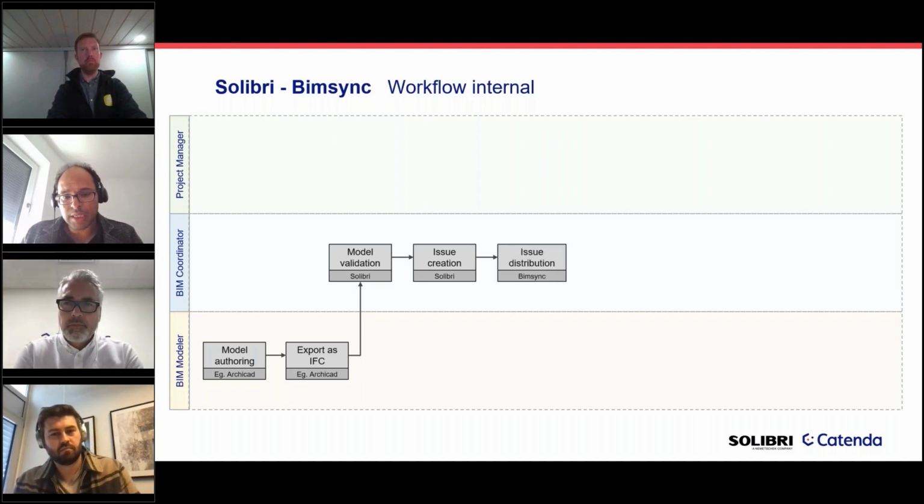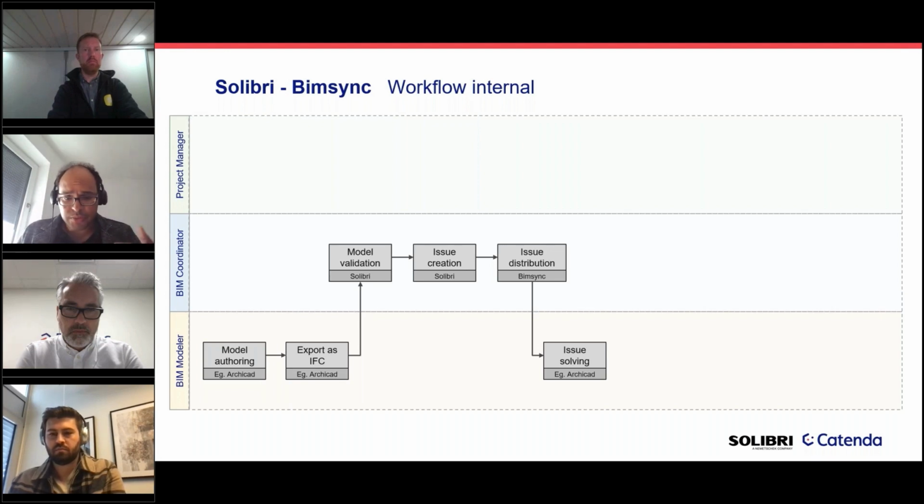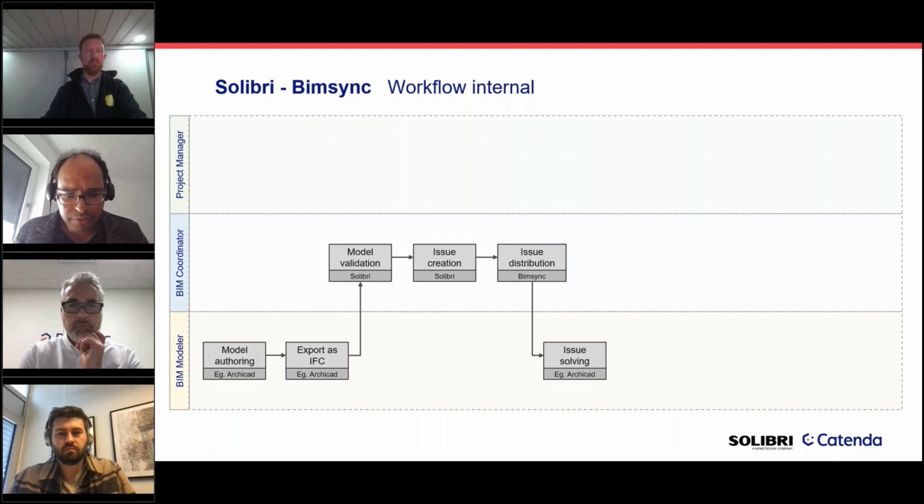The issue distribution, this is when Bimsync comes in, because we want to make sure that the issues are not duplicated, that if I have one issue, it remains one issue no matter how many people or project parties are involved in it. And then once the issues are distributed with Bimsync, I could open the issues directly using Archicad or any other authoring software, and the viewpoint will be recreated in my authoring software. So I know exactly what objects are in this issue.